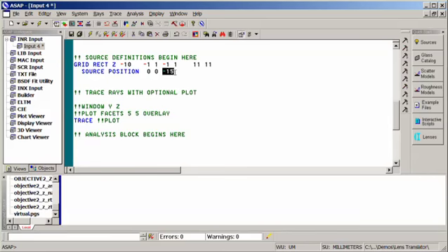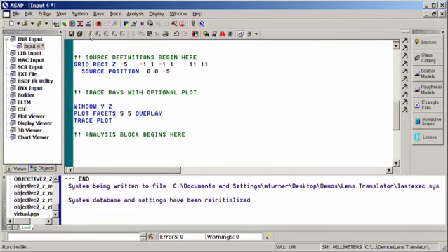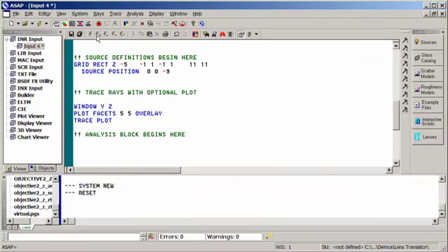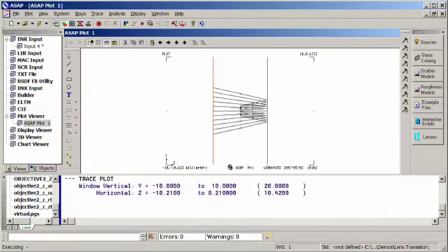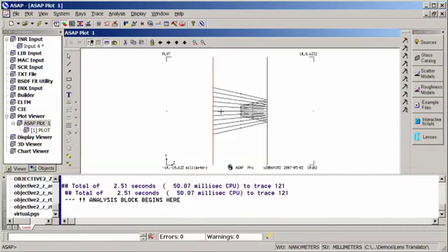Now these won't fit quite with the coordinate system I've selected, so what I'm going to do is make this a -9 just inside my detector, and I'm going to start looking at the rays at a z position of -5, and what we'll now do is just do a little bit of a ray trace. The 2 exclamation points indicate comments, but again, let's just run this file. And as we see, our rays are diverging from our source, which was actually located back here, reflecting off our mirror and being captured by our detector.